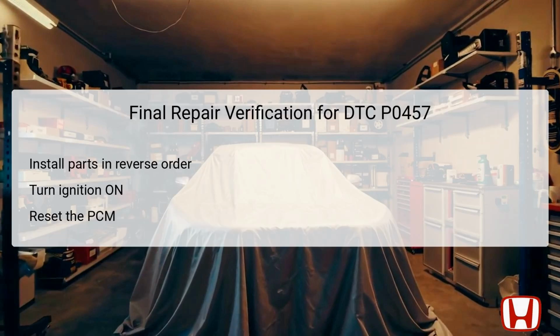Finalizing the repair process involves a thorough verification to ensure all components are correctly installed and the issue has been resolved. Begin with turning the ignition switch to the lock position, followed by reinstalling all components in the reverse order of removal to ensure nothing is left out. After securing the parts, turn the ignition to the on position to power up the system. Use the HDS to reset the Power Control Module, PCM, which controls the vehicle's engine operations.